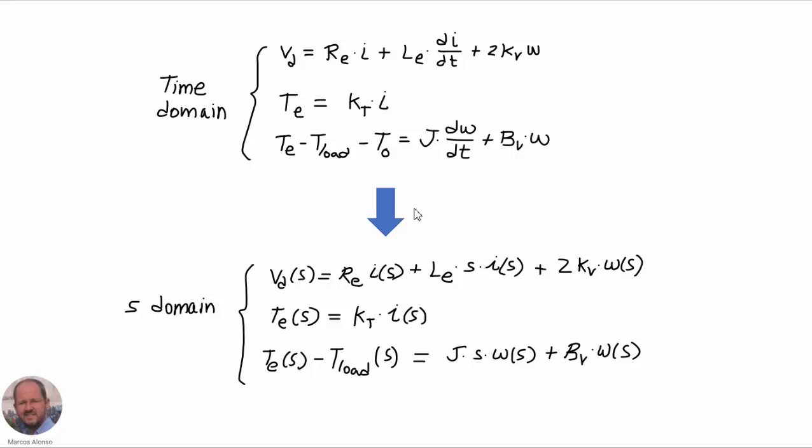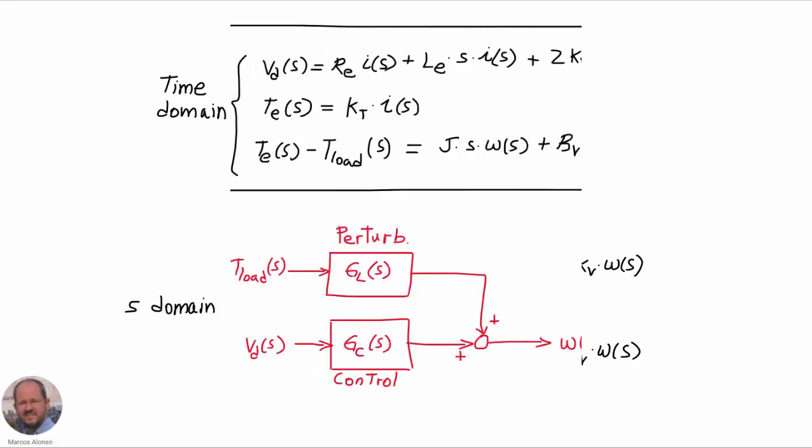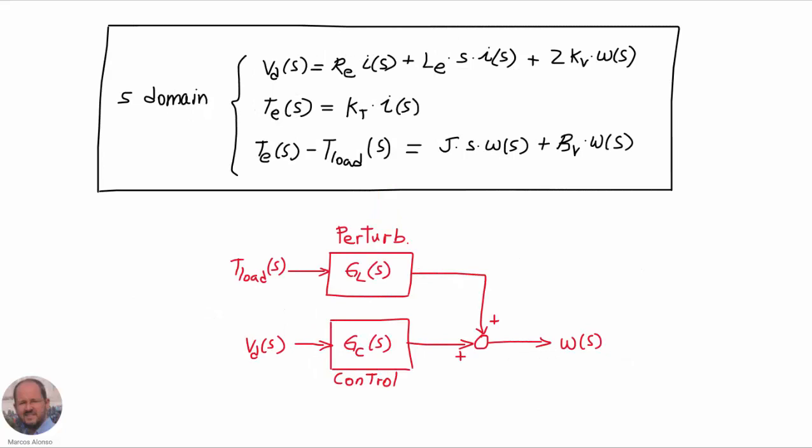So then we can take the Laplace transform of these differential equations, and then we will obtain these expressions here directly, from which we can obtain the complete dynamic behavior of the motor. So summing up, we have here the equations that we need to model our motor with all the variables in the s domain. These variables represent small signal changes in the different variables, as we know. And then here is the representation of the behavior of the motor.